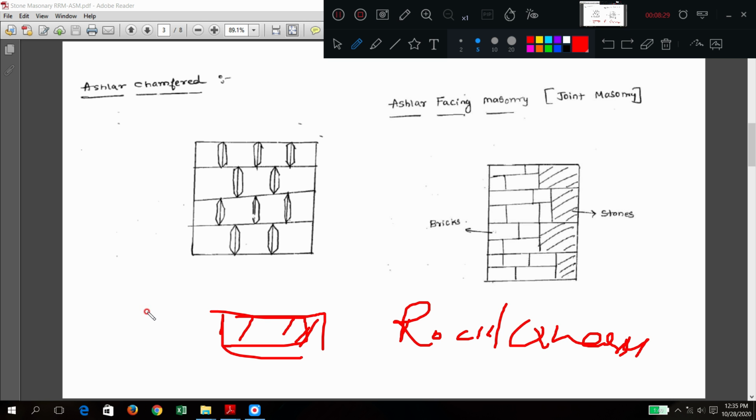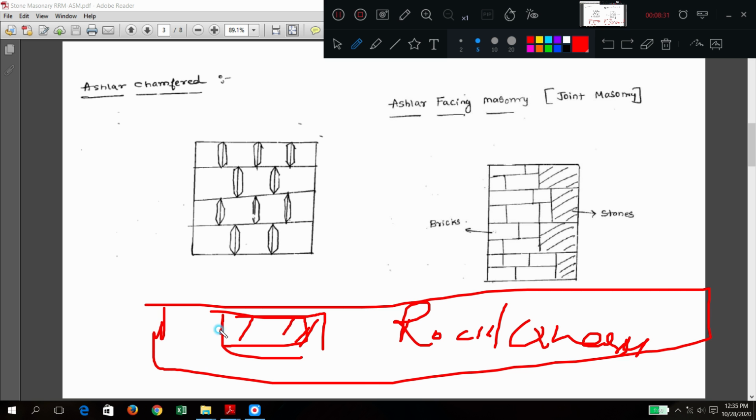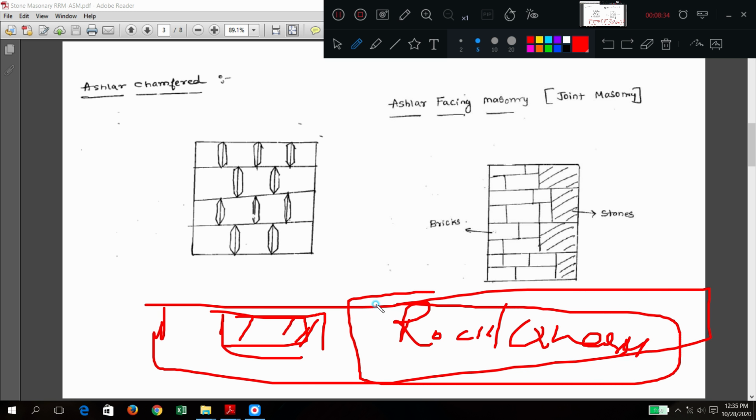For that diagram I have not put it, but you understand that the surface is almost a quarry type of structure when you see it. That's all, simple. Bottom, side, everything is very smoothly chiseled, everything is fine refinement, but the surface appears directly as a rock type of structure, or a quarry type of structure. So those are called ashlar rock faced or quarry faced.